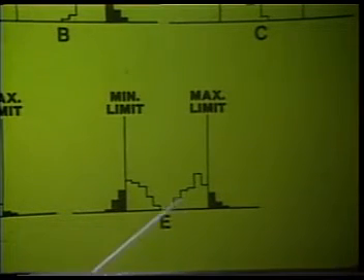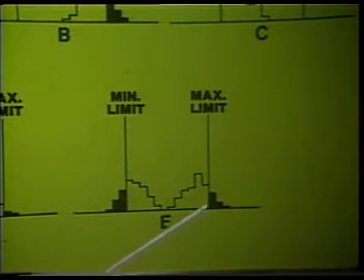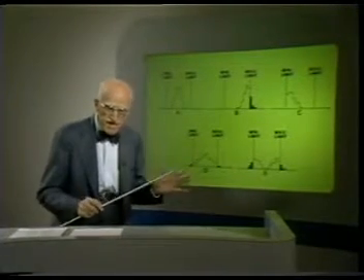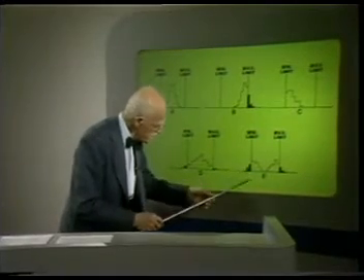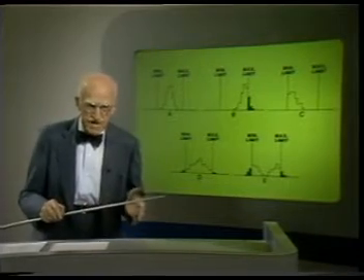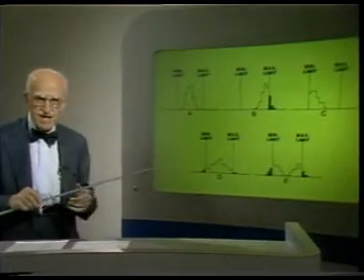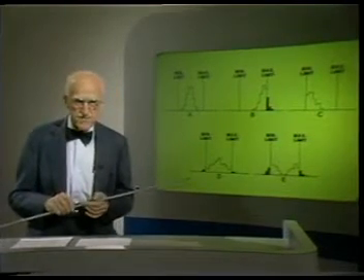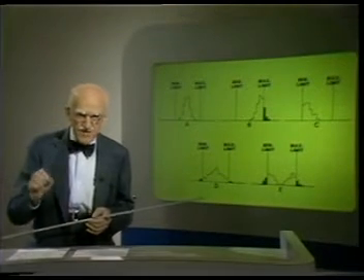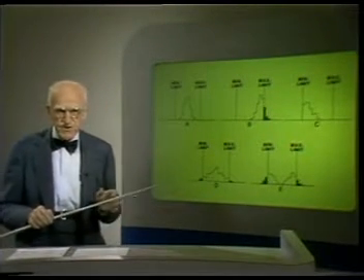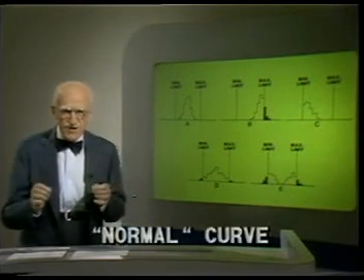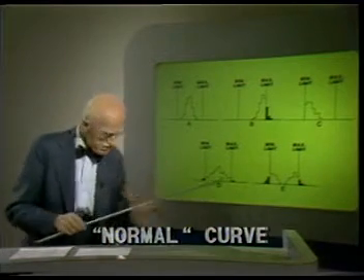Here again, we have a high percent of defectives, both oversize and undersize. This is due to a mixture of product from two different off-centerings of the same capable process. In those histograms, it was easy to judge by eye whether the process could hold tolerances. We can go further. We can compute process capability in numerical form. The simplest cases are those in which the frequency distribution has the familiar bell-shaped curve called the normal curve. Here's how it looks.